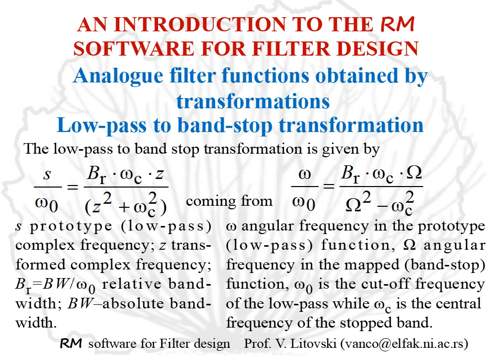And finally, the low-pass to bandstop transformation will be discussed. The notation is similar, with the meaning of BR being different. Now, BR is the relative width of the stopband, of the suppressed band. These filters are of course known also as notch filters, but that is mostly associated with the ones which suppress only one frequency. Here we are speaking about suppressing a band.